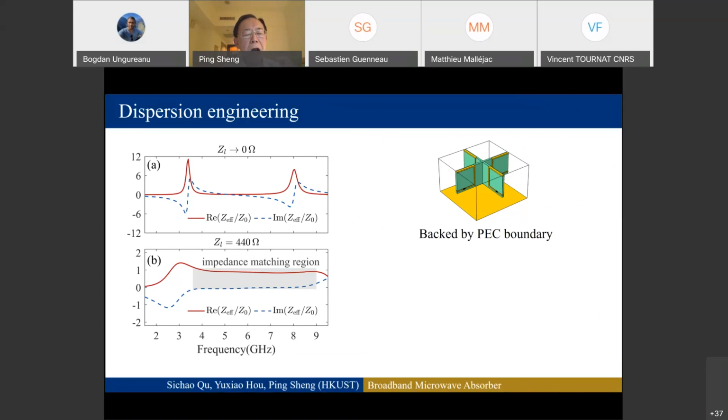These are the high magnetic permeability we want. And now what we want to do is to spread these high magnetic permeability between the two magnetic resonances so they can achieve impedance matching. And how do we do that? We just put some chip resistors at the bottom of the metallic ring. Put 2 of them symmetrically on the bottom.